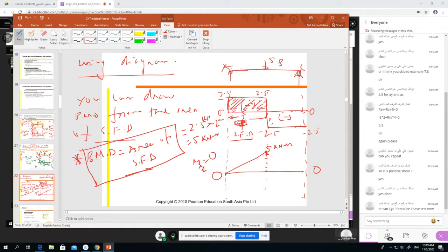If our shear force diagram goes horizontally, our bending moment diagram will be inclined. Okay, and the result is plus. So we write down here plus, and we go upside plus. Then we are here, right? So the bending moment at B, we have plus 5, right? Plus 5.